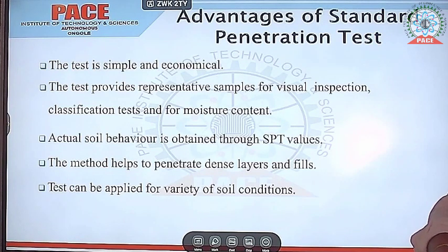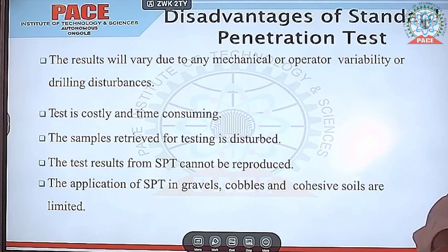Coming to the disadvantages of the standard penetration test, SPT: the results will vary due to any mechanical or operator variability or drilling disturbances. The test is costly and time consuming. The samples retrieved for testing are disturbed samples. So, the test results from SPT cannot be reproduced. The application of SPT in gravelly soils, cobbles and corrosive soils is limited. So, these are the disadvantages.